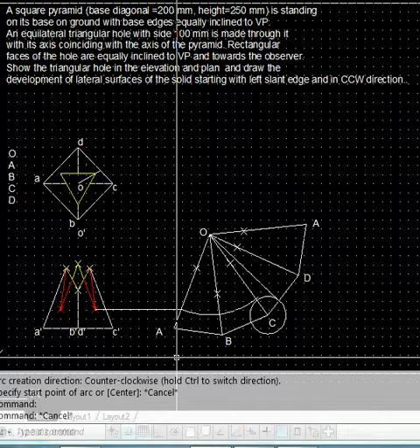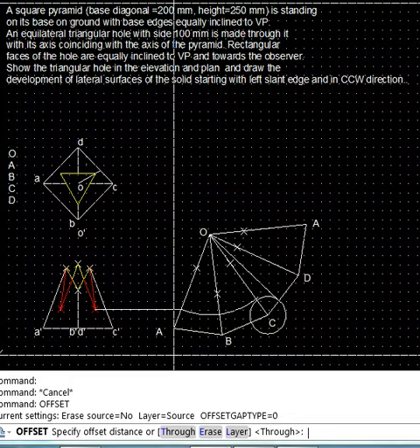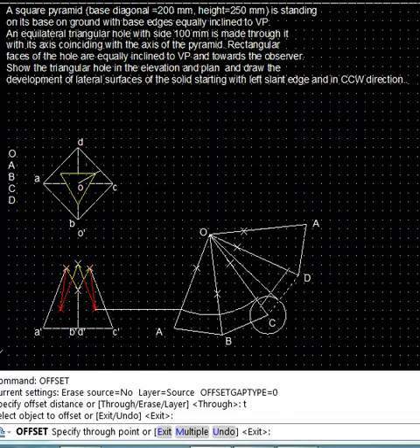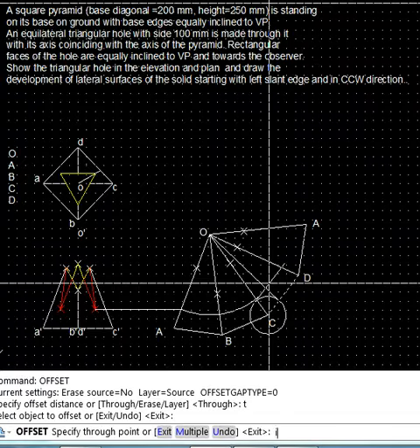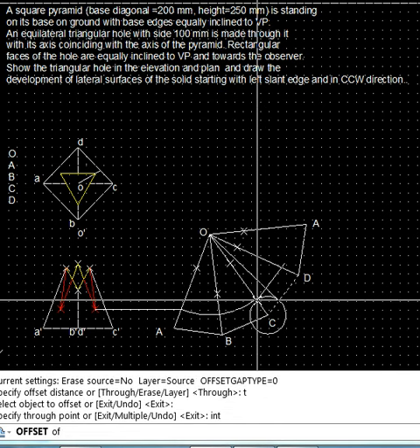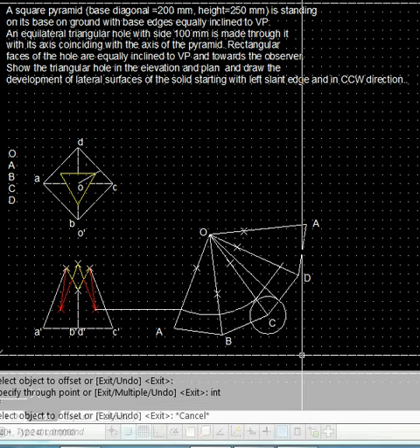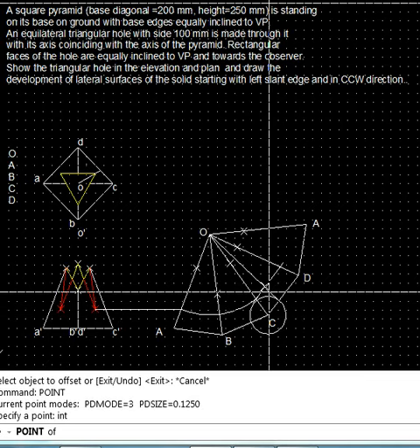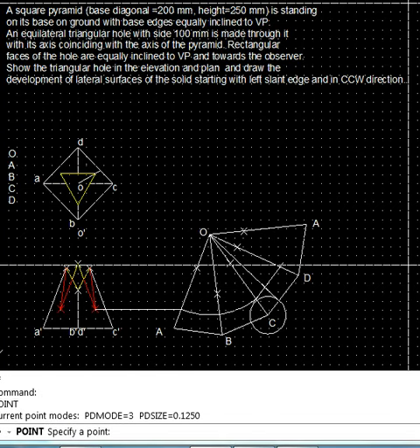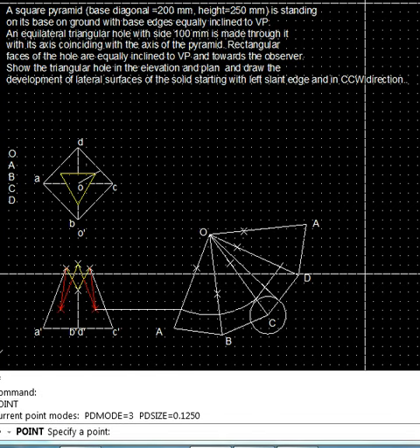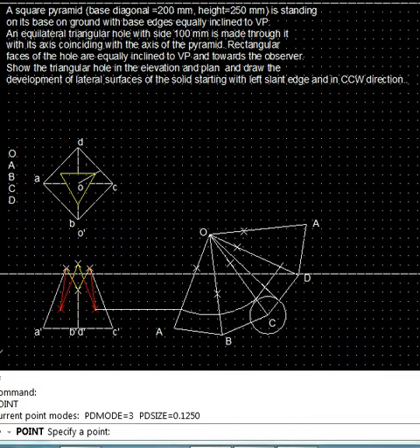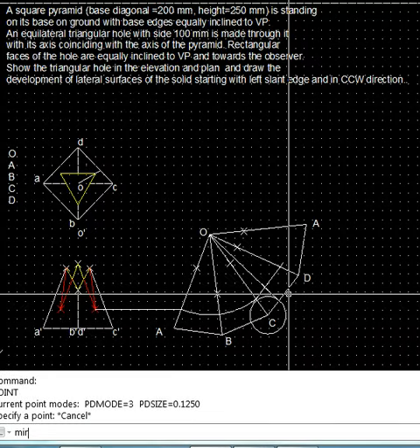After that we will use the line parallel to the base. So we offset the base itself through the point, passing through this required point. So we get the required point here. We mark this point, and we also know that it is as much distance from OA as it is from OC. So same way we will locate it through the mirror command.